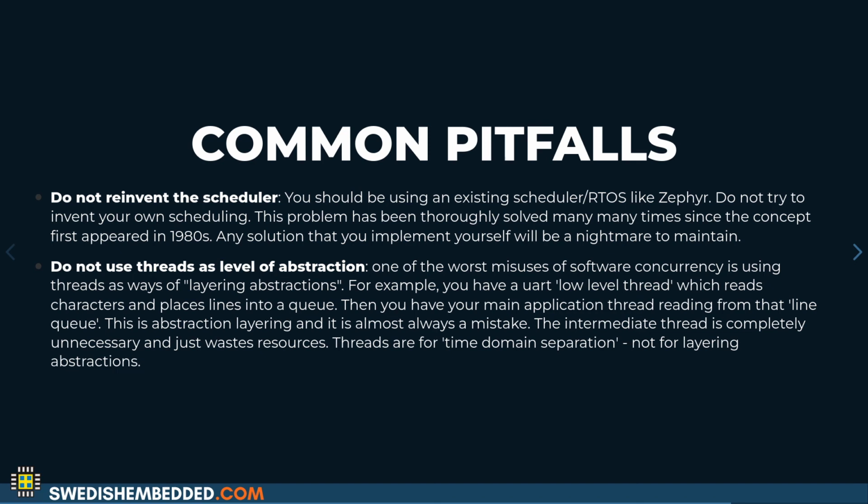There is this generic concept of basically managing the CPU and managing where it will go next. And there has been a lot of research put into this. So there's a lot of code that's already been done, that's already been tested, that is provided to you as real-time operating systems. And there is really no reason not to use it. So the biggest pitfall here is if you try to implement all of this yourself, unless, of course, you're doing it for educational purposes.